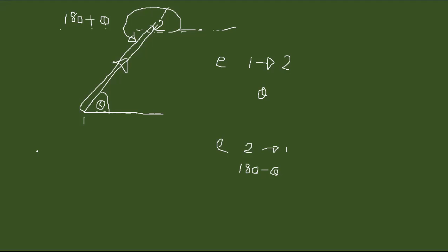And this is the stiffness matrix if we consider this element. So I will write K element. That would be the area, Young's modulus, length, so there will be two nodes.